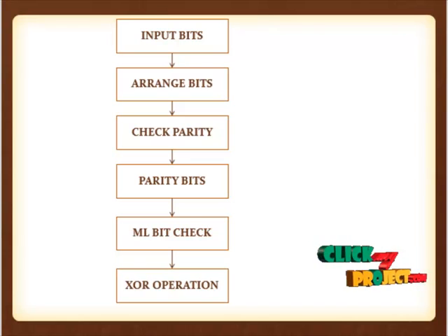In this process we first find the maximum likelihood bit range of the neighboring bits, then decode using the MLD algorithm. The MLD algorithm does the bit check process. We correct the error bit by checking the lost bit from the shift register and the bit from the majority logic circuits. In this error correction stage we use an XOR gate that changes the error bit if there is a change in the bit. It compares the lost bit from the shift register and the bit from the majority logic circuit, and finally corrects the error bit.